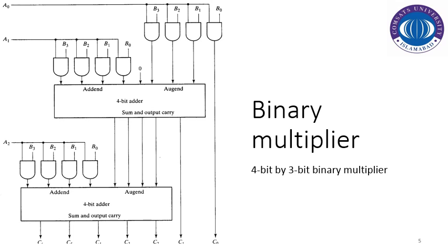So if you see the diagram here, we've got 12 AND gates. Since in our previous slide we discussed that the product terms are being represented by the AND operation, and we've got 3 partial products. So the first two partial products are added with the first 4-bit adder, and the result of that summation is added to the third partial product in order to produce our final result.